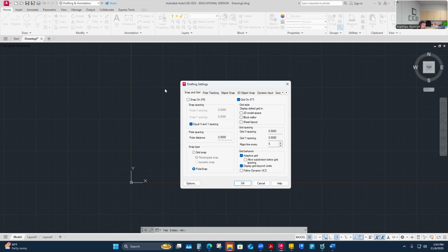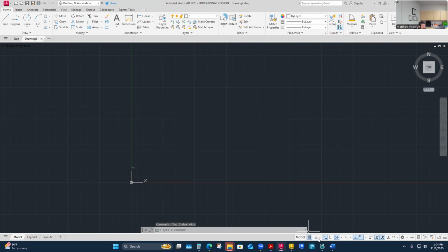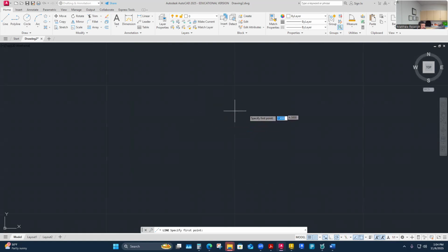That can be helpful to know: what are the default grid spacings? Well, they're 1/2 inch. Can you change them? Yeah, you can. I typically don't. I don't have to draw on those graph spacings, but if you have grid snap selected and it's turned on, blue, then when you're in a command, it'll look kind of jogging like this because it keeps me snapping to that grid. People used to draw like this, and sometimes there are reasons why I need to draw this way for specific prints. In our case, we won't need to worry about being snapped to the grid whatsoever.